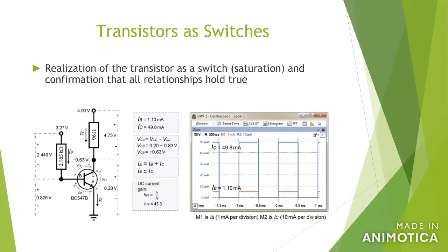So you don't use the power on Raspberry Pi to drive a motor, because the power on Raspberry Pi only provides very low current. If you use that voltage to drive a motor, you will burn the Raspberry Pi circuit. So you have to use a separate power to drive a motor. That power is connected to C and E, and you can consider this as a motor.